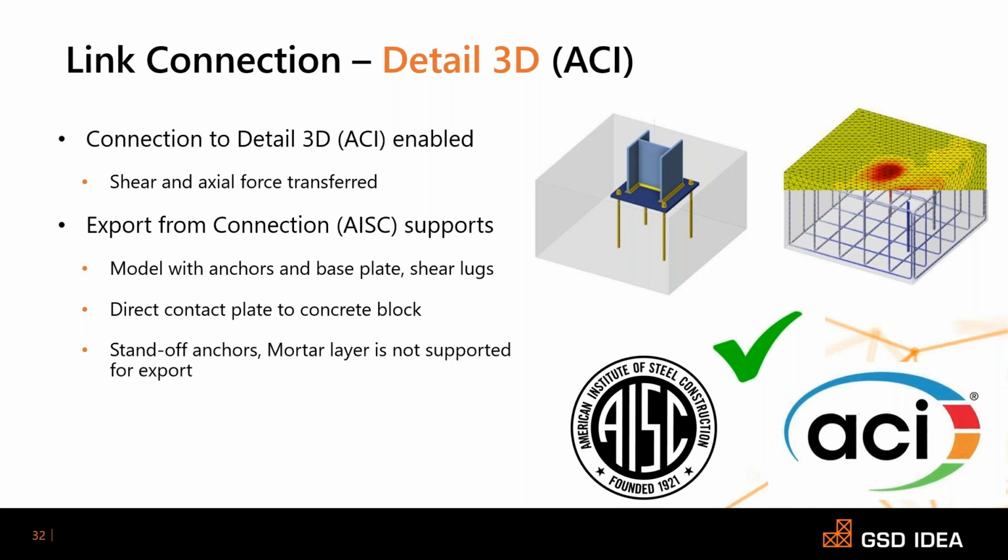If using the AISC application, now you can transfer the data into the detail 3D, in which you can check all your reinforcement details as well as the concrete checks using ACI. Basically, what data can be exported is the information about the base plates, information about loading, information about the anchors, and also the concrete block. However, as of now, standoff anchors and mortar layers are not supported for the export.